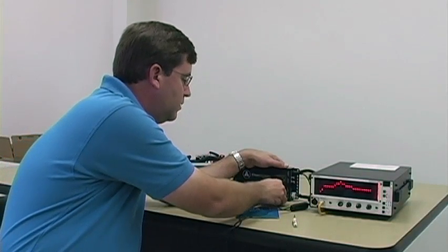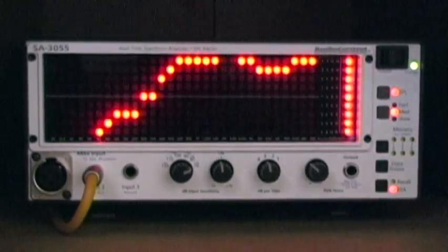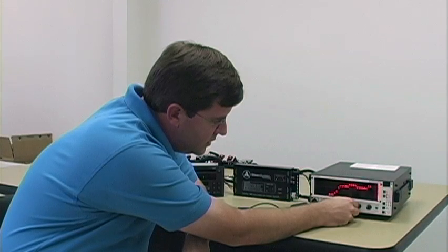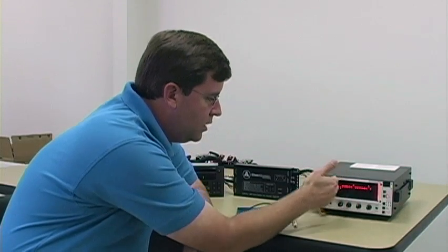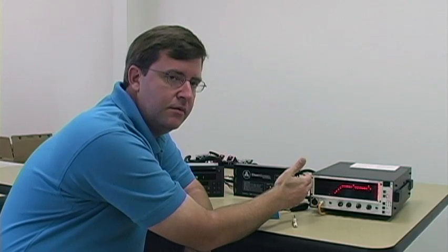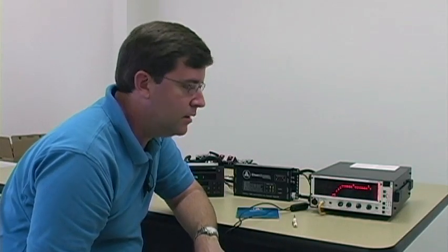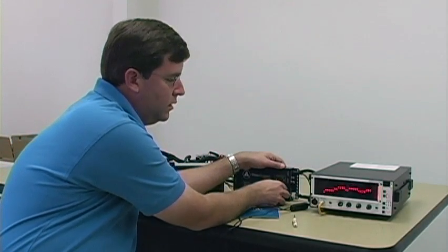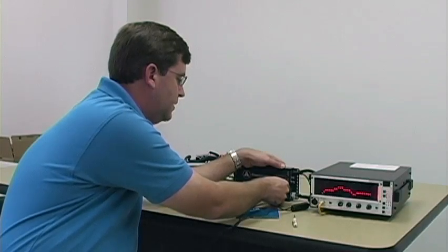Let's see what the CleanSweep started with on this signal, what it had to work with, and you'll see why there was a problem. Oh my goodness. Okay, we have a very severe high-pass filter applied at a fairly high frequency in this system, right around 250 or 300 hertz or so. So all of the information below that frequency is missing from the signal, and the CleanSweep, needing a full range signal, was not able to rescue a corrected response from this input. Okay, once again, I'll show you what the CleanSweep tried to do with it, but the result is not a satisfactory full range flat corrected response.